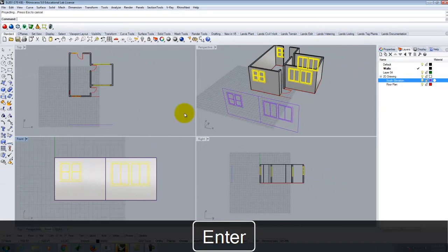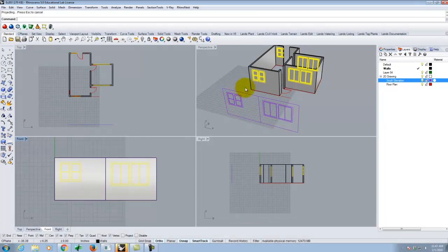And you'll see that it will take these lines and it will throw them across each of these surfaces straight through the building. Now, because this was a contained polysurface, right, it threw the lines on this wall over here and gave me a half of a window. Okay? Now, if I had drawn the elevation on the opposite side, right, I wouldn't worry about using this window, okay, because I do the project the opposite way.